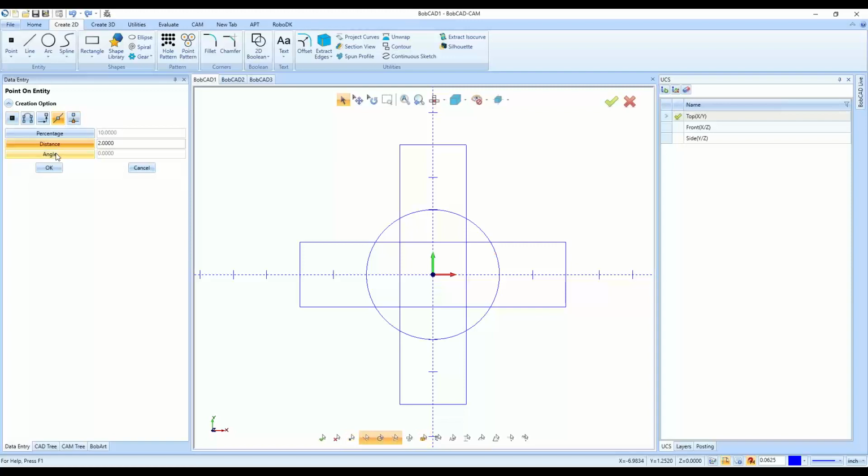And then an angle option, we can go from a certain angle from a line or from an arc, or mostly from an arc, I believe. So this is the 0 point from the arc. We could say 90 degrees from that point going around. You can see up here at the top, or downward. Actually, no, sorry. It only goes from this 0 point all the way around this way, counterclockwise. So if we said 270, then we can do that location down at the bottom.